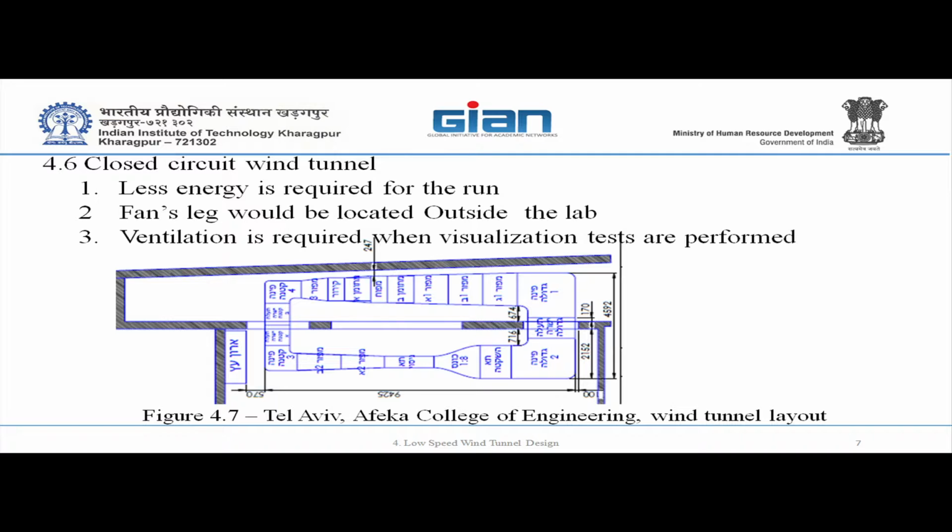critical. So usually you would prefer to put this heat exchanger ahead of the fan, but there are wind tunnels where you use your vanes in order to have some pipes and cool your system, which will be, I mean, manufacturing turning vanes to include the tubes will be costly. So maybe it should be considered.